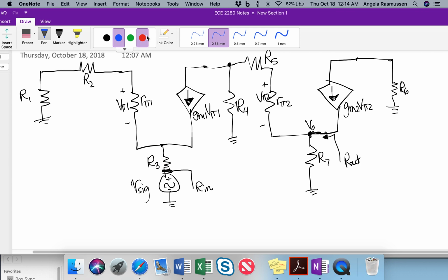So to find Rn, you ignore the input source, and you're going to take the node pathway to ground. So here, as we come in, we can go two different routes to get to ground. So we can use the resistance reflection rule to remove or ignore this current source, and in order to do that, we are located at the emitter side, because we're trying to find the node at the emitter side. So we're going to divide these resistors by beta plus 1,